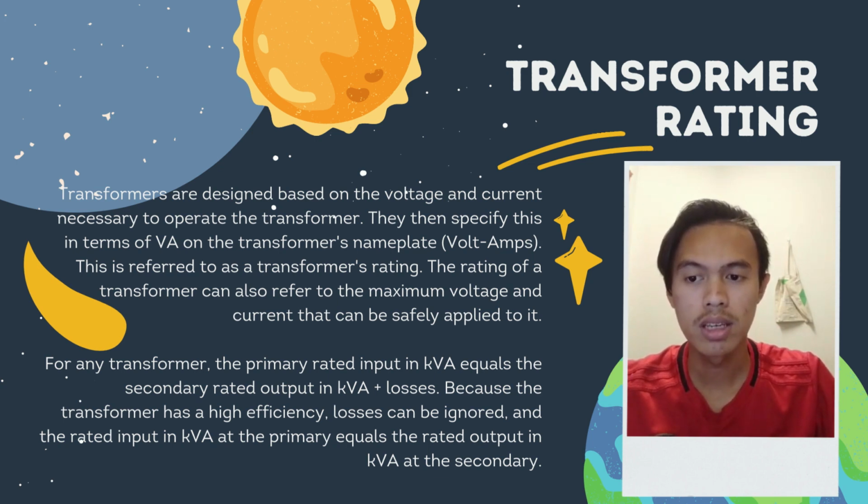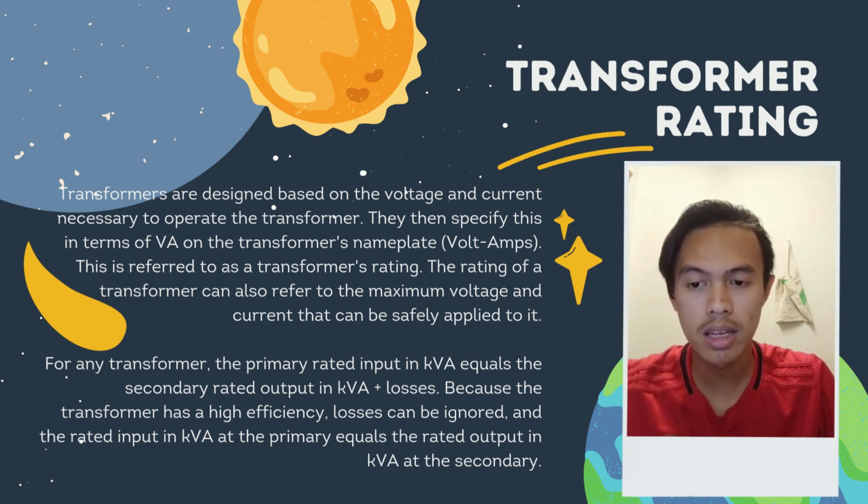A transformer rating is determined by temperature rise, which is determined by the transformer loss. Using the correct cooling system, the temperature can be kept below an acceptable level. The higher the rating of the transformer, the more effective the cooling system must be, and vice versa. The rating of an electrical machine is indirectly determined by the loss existing in the machine for a certain cooling system.